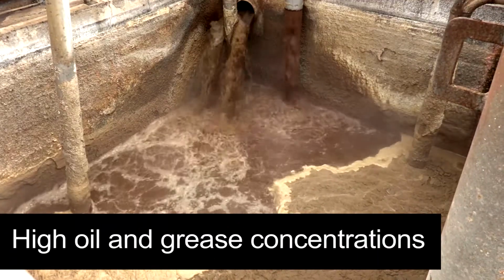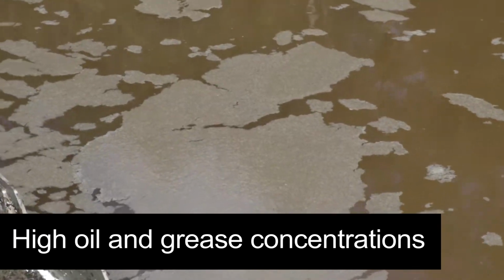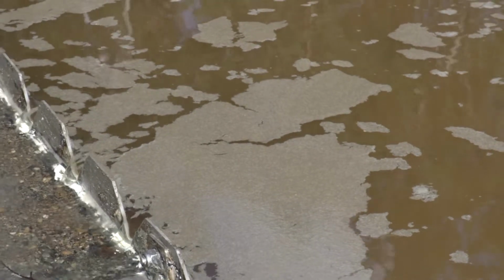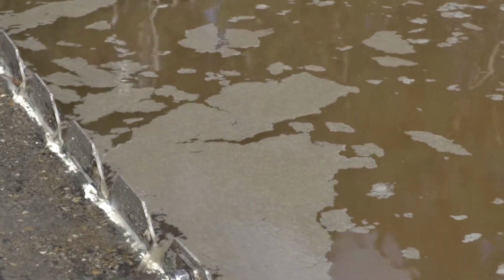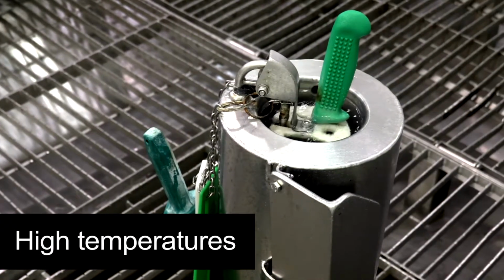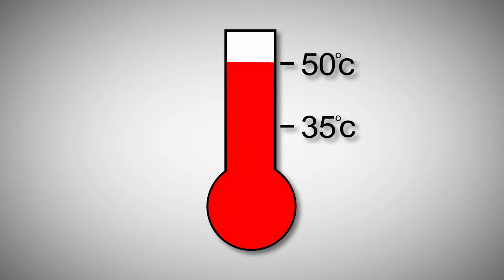The wastewater is usually rich in oil and grease, which hampers downstream treatment processes and produces floating scums and crusts in downstream pits, basins and ponds. It is common to measure temperatures as high as 50 to 60 degrees Celsius in red waste streams from meat plants, especially where rendering is part of the facility. This is too hot for downstream biological processes in the treatment plant. The preferred temperature is less than 35 degrees Celsius.